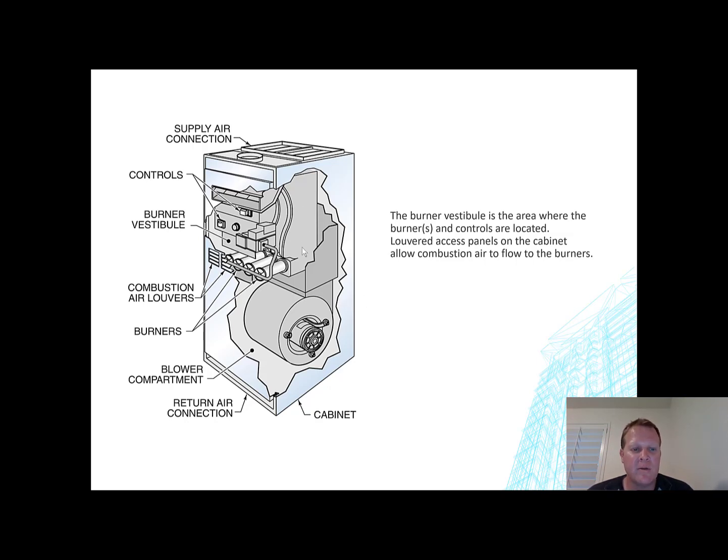And by the end of this whole section, I think you've seen how cooling tower to chiller to coil inside the air handler, that's all heat exchange. It's just moving heat from one spot to the other, and trying to get heat outside of the building. So we talked about how this is the blower section.